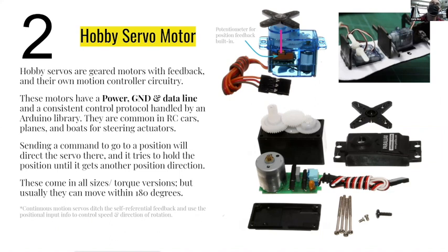You can see the motor inside here. There's a gear train across the top. There's usually a little potentiometer right here. These have a circuit board in their bottom that's keeping track of how much they've spun, and a potentiometer that can track how much it's rotated in one direction or the other. So these are actually motors that have some brains to them. They have a full, complete loop of feedback, and they're really useful in RC vehicles because they can move and hold turning mechanisms or actuators. You can sort of imagine the flaps on a little RC plane going up and down, if you can imagine interesting linkages that go between these motors and where they're headed.